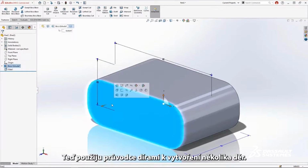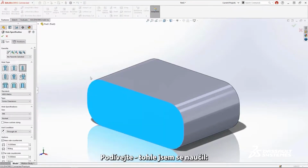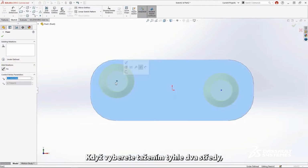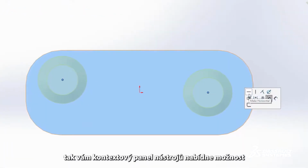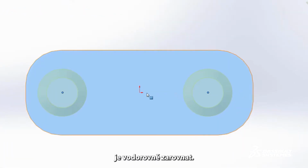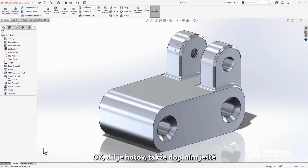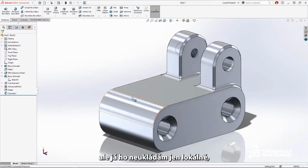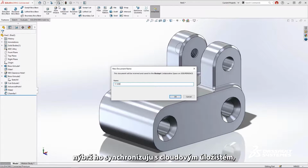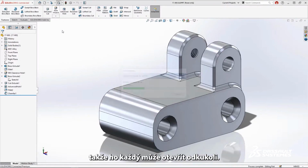Now, I'll use the hole wizard to make some holes. Hey, I just learned this. If you box select these points, the in-context toolbar gives the option to horizontally align them. Okay, the part's done, so I'll add some properties and then save. But I'm not just saving a file, I'm syncing to the cloud that any of us can access from anywhere.